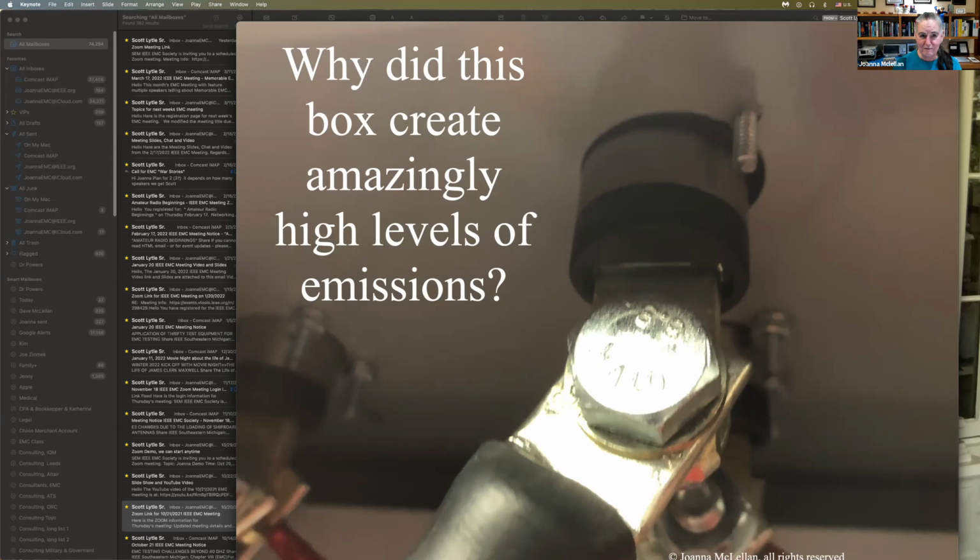And you see where that coax connector has 4 holes. The technician building the box drilled 1 hole, put a bolt through the hole, and didn't bother to put a nut on it. All the RF current that was traveling along the shield of that great big hunky orange cable was wandering all over the place, going exactly where it wasn't supposed to go. And that's why the room had hideous amounts of RF.